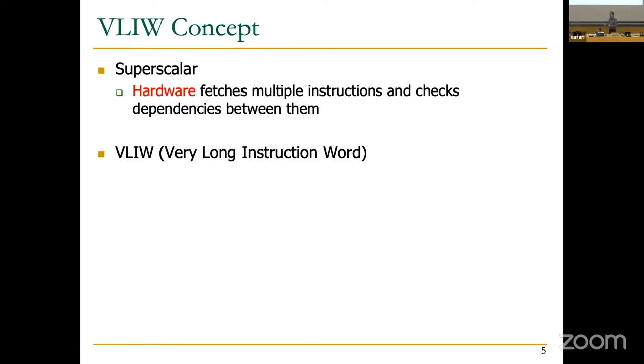So it's basically a multiple instruction fetch, decode, execute paradigm, but hardware is responsible for doing all of this, right? What the compiler generates is sequential code as we would expect in a von Neumann architecture, right? It's essentially what we've been used to, except hardware extracts parallelism out of it every cycle. Okay. So everybody's familiar with superscalar, right?